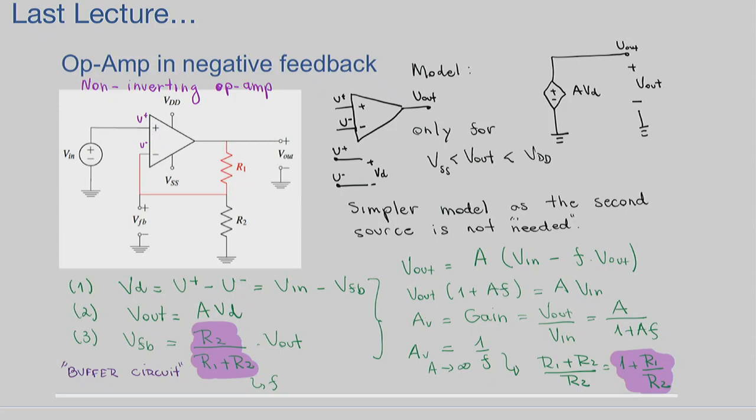So that was a problem. And we were like, okay, nice try on the design, we need to change things. Let's get rid of the loading effect by isolating the DAC from the speaker. And then we started looking at what we could add to the operational amplifier in order to isolate.